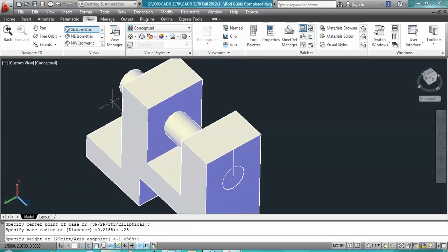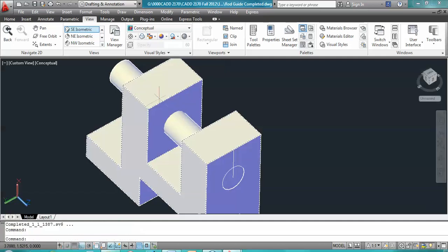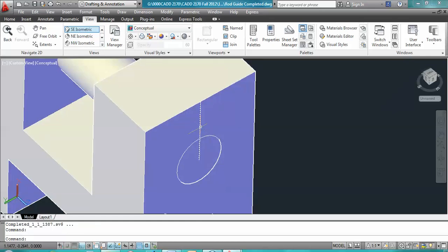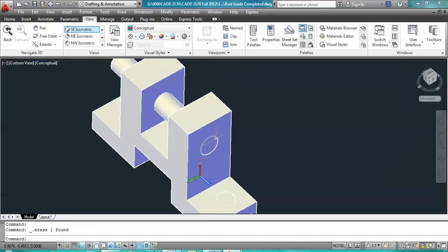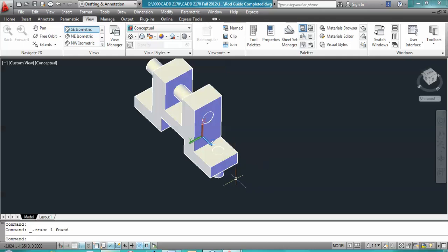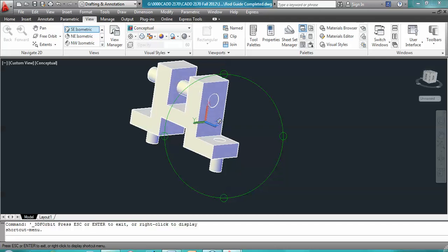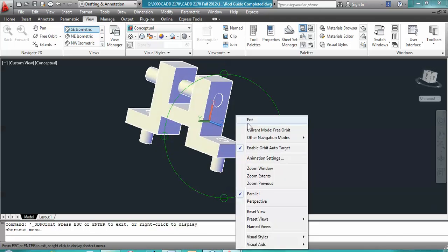And since it says 2 times diameter 1/2 inline, it means both cylinders will be the same size. Click and erase the reference line. And now subtract, so we're going to rotate the object a little bit so we can select all at once.